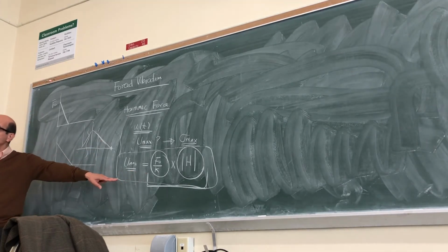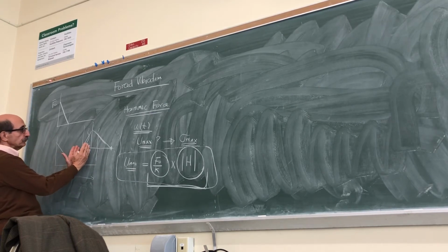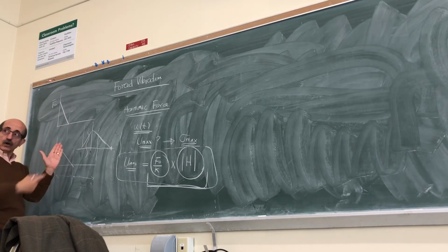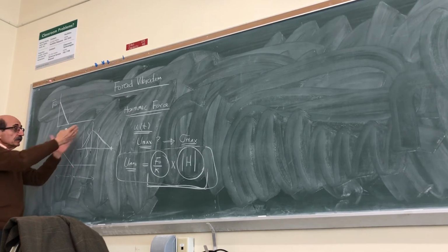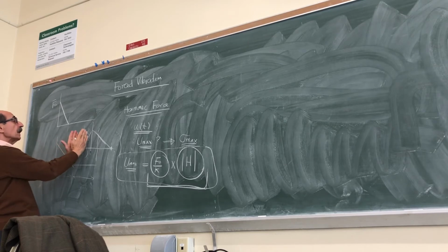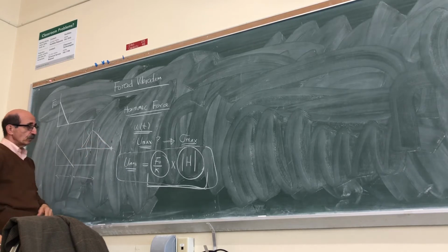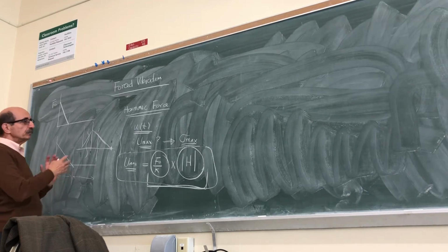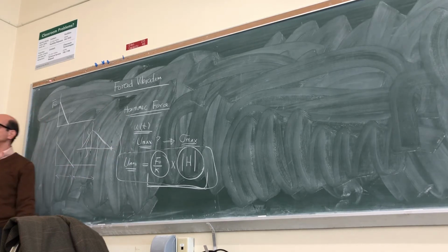The only way we can do it is by taking the derivative of the function that we derived here, equating that to 0, finding the time that corresponds to that maximum value, and seeing if the displacement that we get here is really the absolute maximum, or the displacement that we get here is the absolute maximum, and so on. That's what makes the Duhamel integral more involved, and this whole operation much more extensive than what we've been doing with harmonic force.